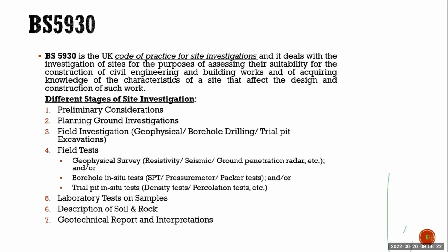Each country will have its own specific standard for site investigations. Here, they are following the code of practice for site investigation, which is the British Standard. Whichever standard you follow, the site investigation commonly has three stages: one is the reconnaissance survey, another the preliminary survey, and third the detailed investigation.